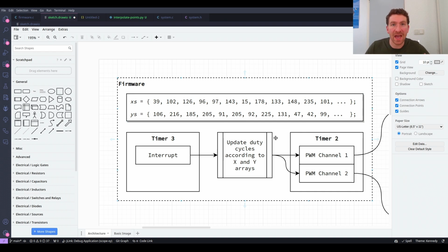And we're actually just going to output digital signals on the microcontroller. We don't have a digital to analog converter on this microcontroller, right? We have to generate digital signals and then somehow turn them into analog signals ourselves. And we're going to look at how we do that in a second. Basically, the idea is that we have 2 channels. These are our 2 pins.